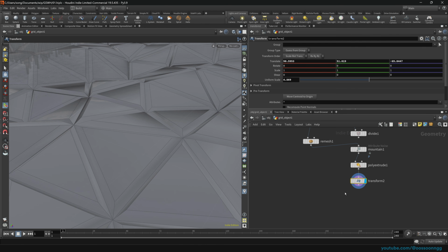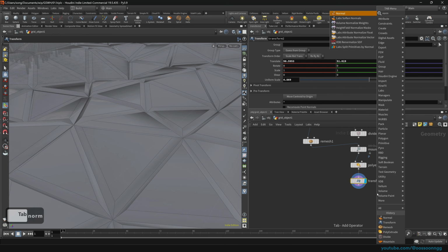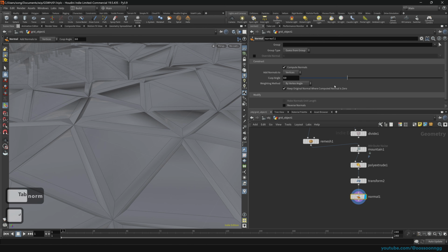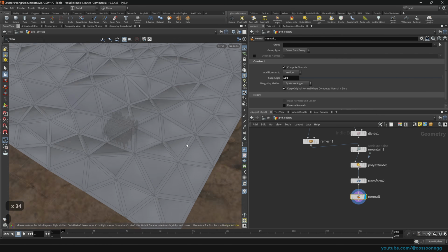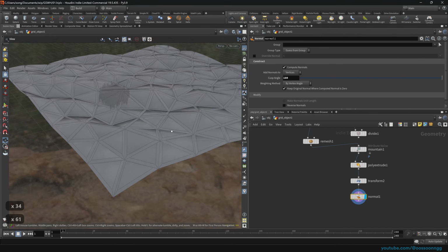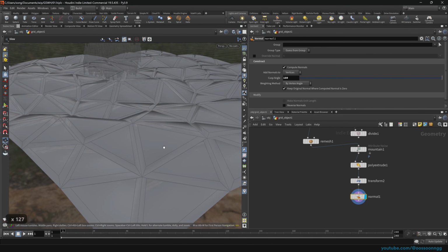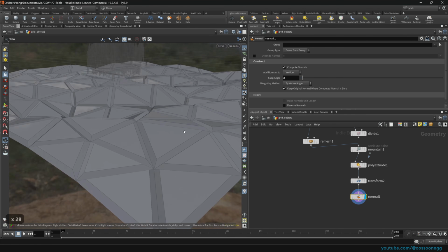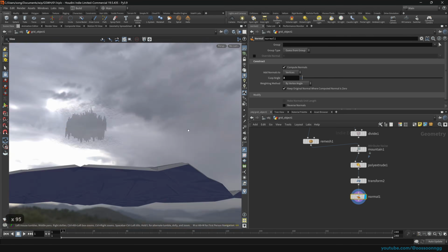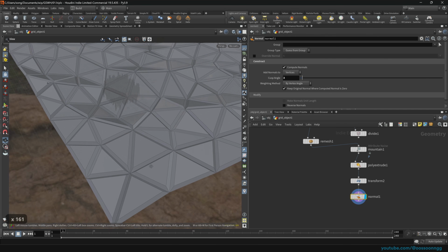If something is not explicitly told to be had, for example, even normals, Houdini will not actually assign normals for rendering purposes. As you can see, if we make the cusp angle 180, it looks kind of blobby, not really well defined. However, if the cusp angle is, I don't know, like 2 or something, it looks really, really sharp, and that is exactly what I want.